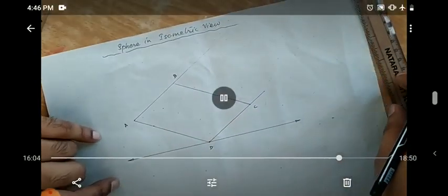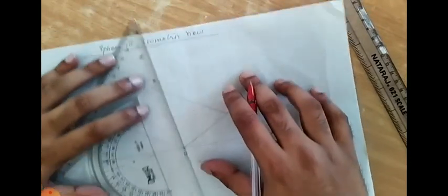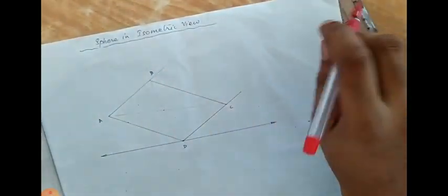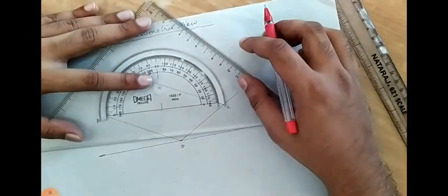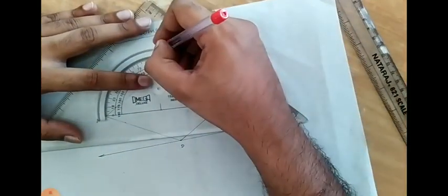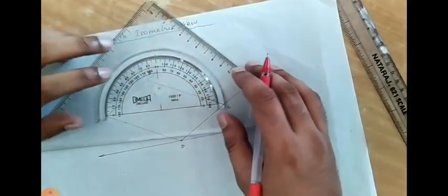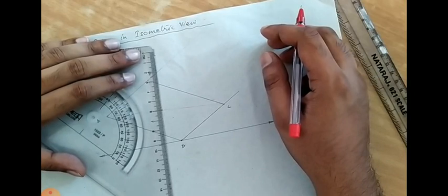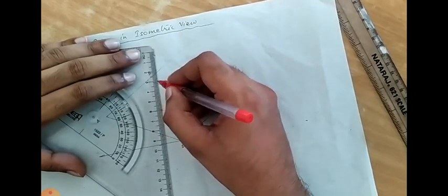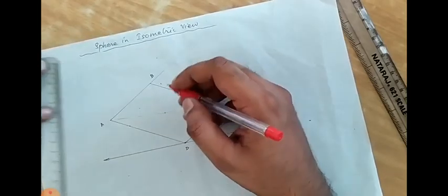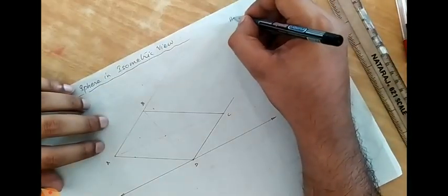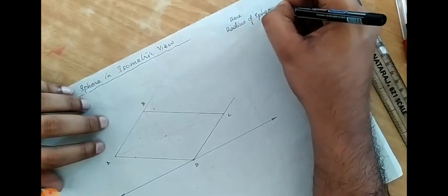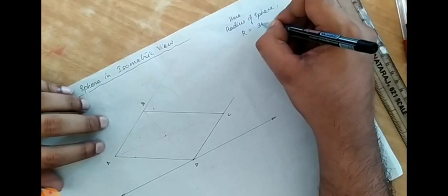A, B, C, D, I have marked the names. Now I am again going to find the center of the rhombus. From the center I have to take the distance so as to mark the center of the sphere above the square lamina. I have to take the distance from the center of the square lamina up to the center of the sphere. That distance, as we have seen in the front view, is equal to 30 mm, which is the radius of the sphere itself. So that height, which is a linear distance, won't change its dimension as it is an isometric view.